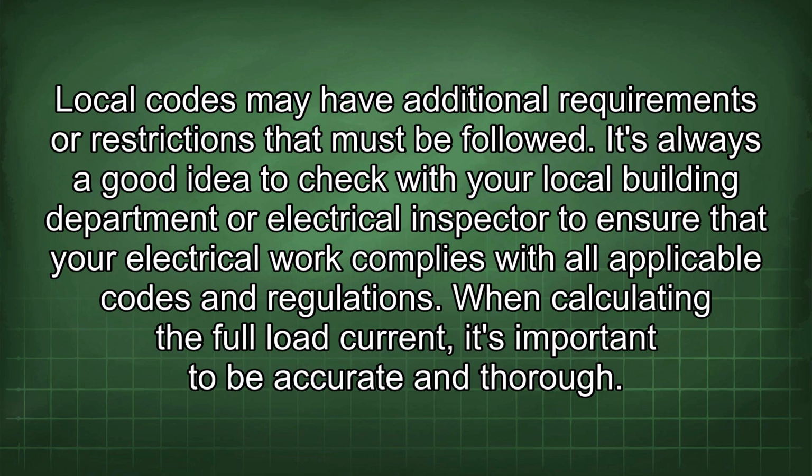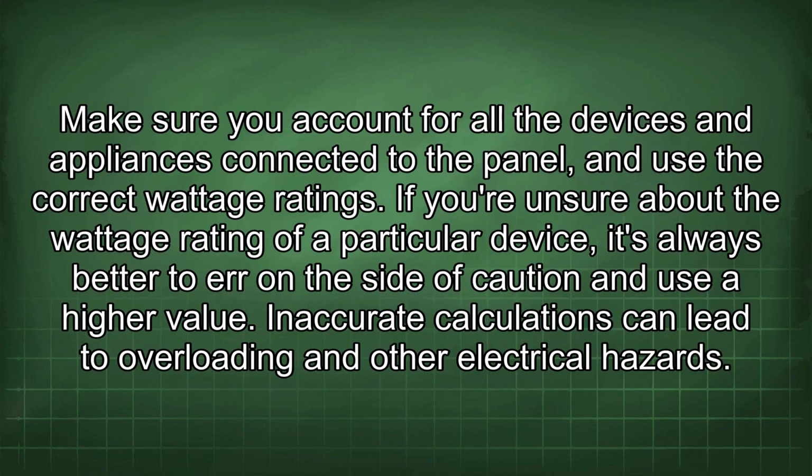When calculating the full load current, it's important to be accurate and thorough. Make sure you account for all the devices and appliances connected to the panel and use the correct wattage ratings. If you are unsure about the wattage rating of a particular device, it's always better to err on the side of caution and use a higher value. Inaccurate calculations can lead to overloading and other electrical hazards.